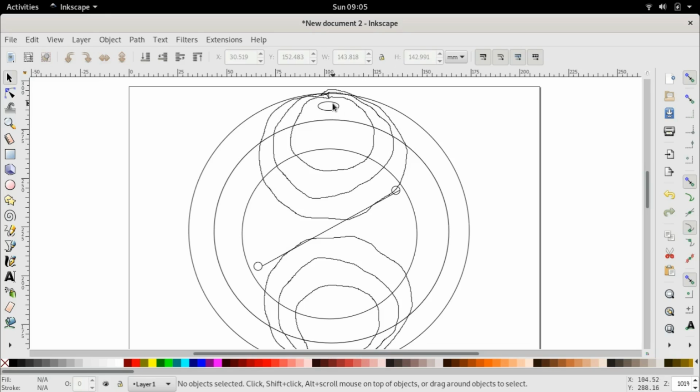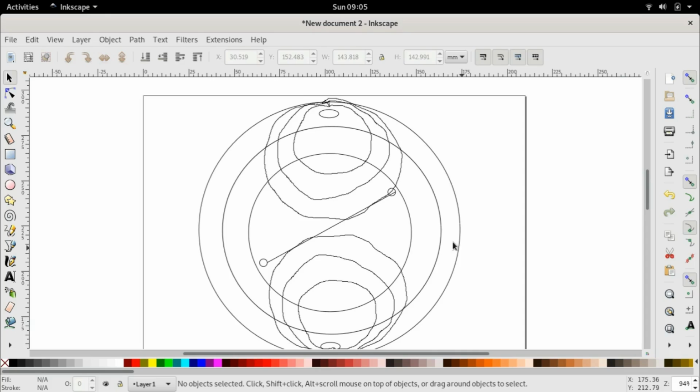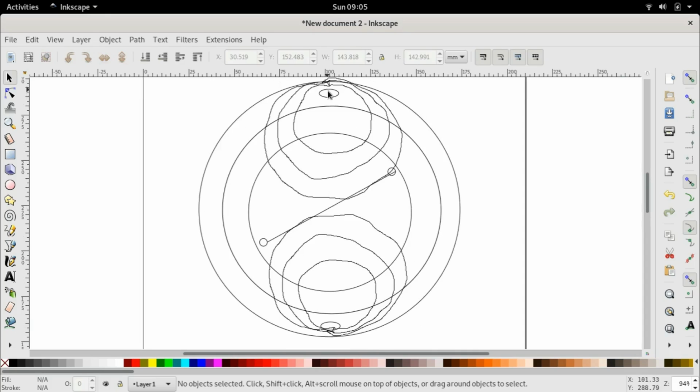So we have represented a simplified stator winding where we say there are only two stator slots diametrically opposite each other in the stator, and the entire stator coil is wound along these stator slots. So we also assumed that in any one of them the current has to enter the page, and in the other the current has to leave the page, because after all it's a coil carrying a current.